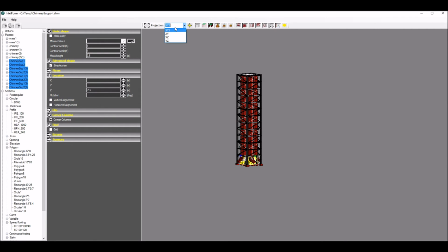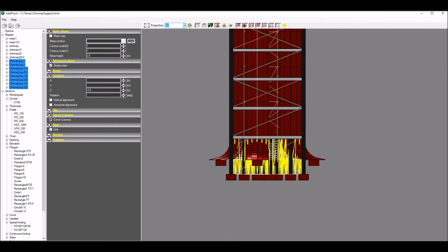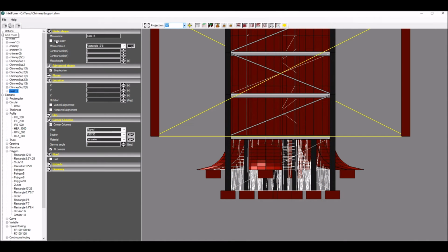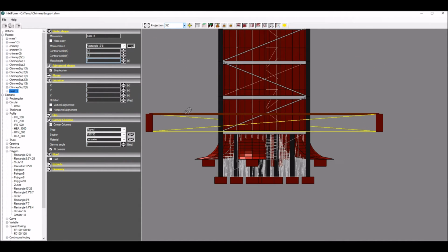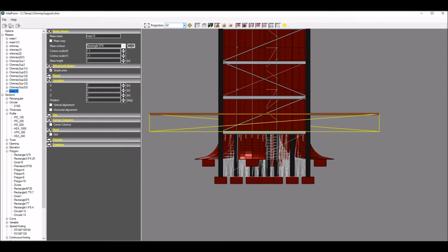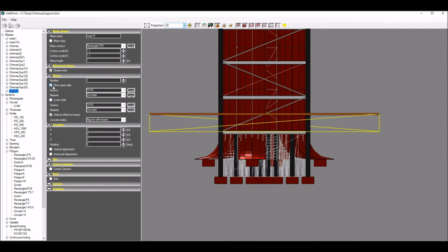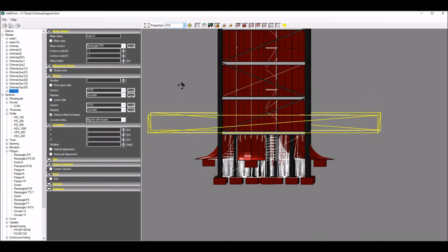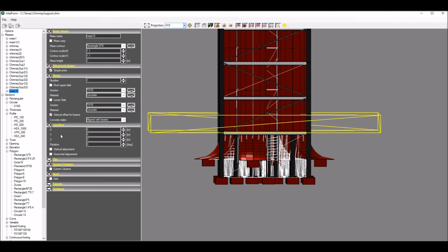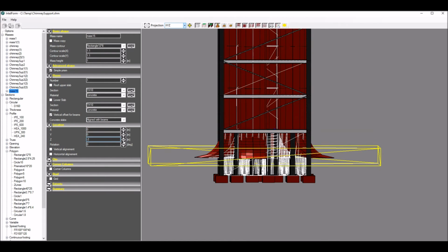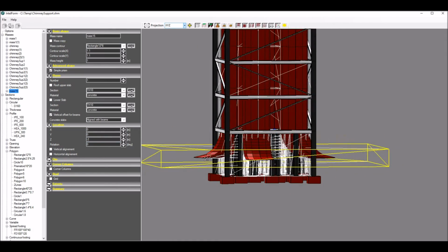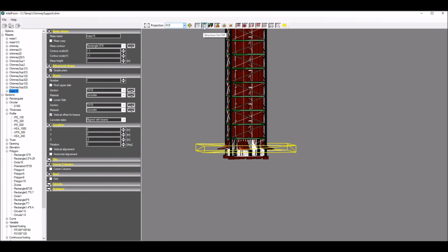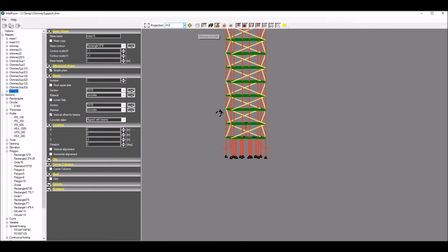Here I would like to draw your attention to the fact that in IntelliForm foundations are created automatically on the columns or walls at the lowest mass level, if no other mass exists below. Sometimes, like in this example, some foundations are redundant and we want to get rid of them. We can simply do it by defining a dummy mass at the appropriate place, without any structural elements. So, we use the already known mechanism of mass definition, but for a different purpose. Here, thanks to it, foundations which were automatically created at the chimney ends have been parametrically deleted.